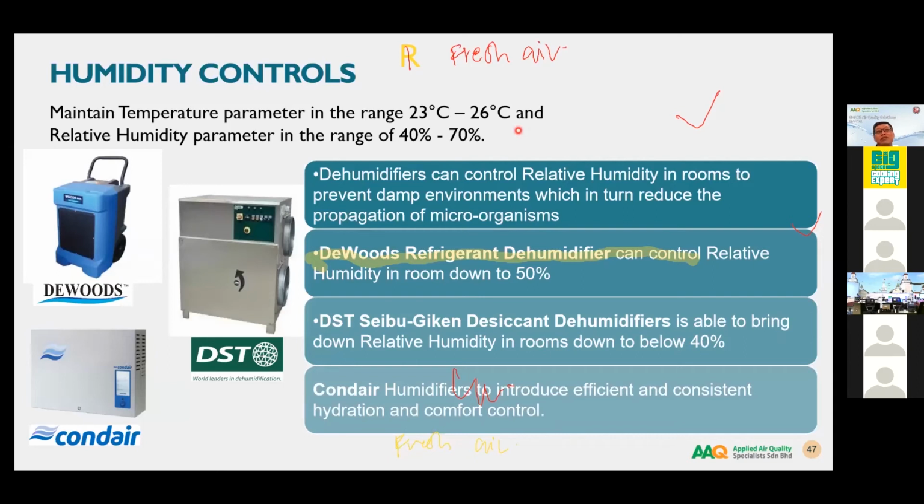But your ACMV cannot be improved. So how are we going to look into it? Maybe you fit in other equipment like an electronic air cleaner combined with the UVGI lamp, the individual standalone. It will help to reduce, or maybe you put in a HEPA filter, those air purifiers you buy, and then help to enhance your indoor air quality. Yes, those can help. But bear in mind, like what I said, the bundle thing from the hierarchy is a must.